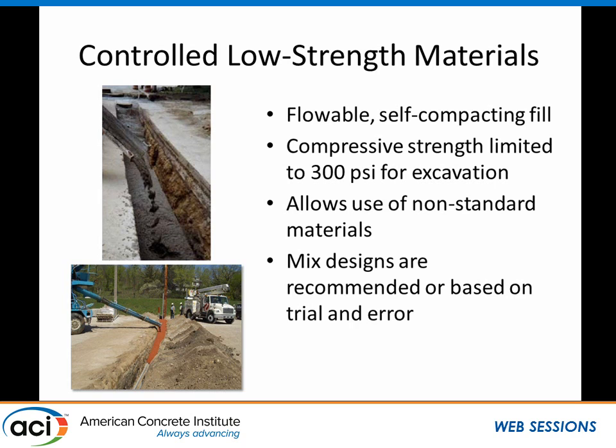And you see an interesting thing being done in the picture below, where they're using it for backfill around pipe and so forth. You can put in some color coding, as it were, and that way if your excavator hits something that's red, they know they're really close to the pipe and start using extra care. The flowability of these materials is a great advantage for filling trenches and anything next to a foundation and so forth.